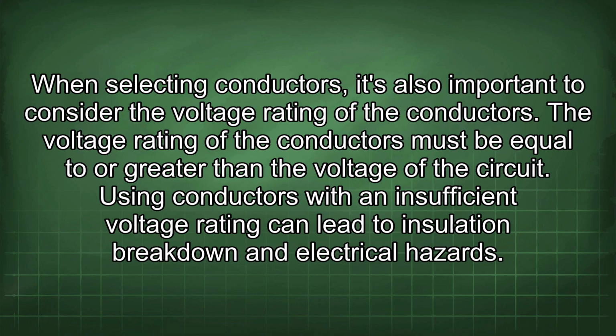When selecting conductors, it's also important to consider the voltage rating of the conductors. The voltage rating of the conductors must be equal to or greater than the voltage of the circuit. Using conductors with an insufficient voltage rating can lead to insulation breakdown and electrical hazards.